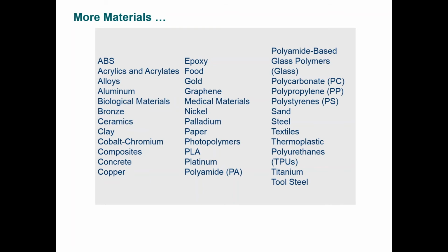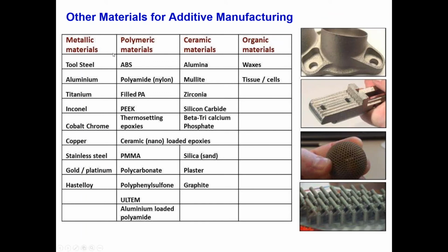Hence, this table is quite telling in that there is a lot of interest in polymeric materials, yet there's also a bigger community that is focused on metals or metallic materials that can be 3D printed versus cast or molded systems. So high performance materials such as titanium are, for example, advantageous because of their non-corrosion properties, or even noble metals such as gold and platinum for the electronics industry. On the other hand, ceramic materials and refractory materials such as alumina, zirconia, silicon carbide are of high interest in various industries and have complementary properties because of their hardness and insulation.